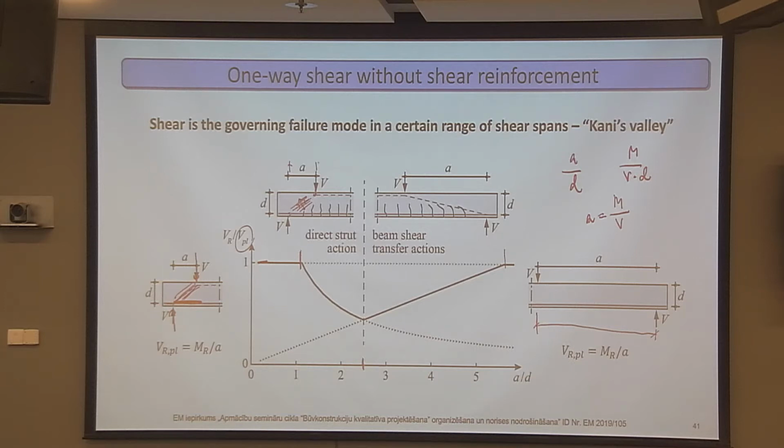So a lot of little cracks will appear in the strut, and its strength will decrease. This is actually what is happening in beams with shear reinforcement, where the failure of concrete is governing, or in Eurocode, V_Rd,max, the crushing of the struts. And in Eurocode, coincidentally, it's also limited by 2.5, the minimal angle of the shear field that you can take.